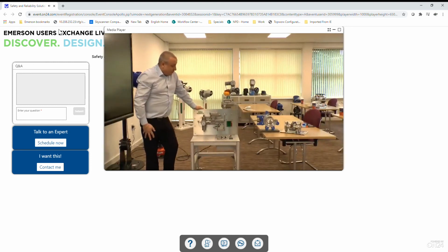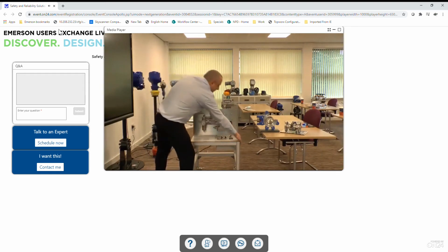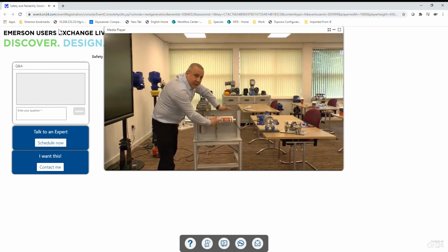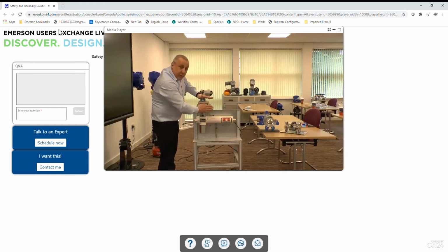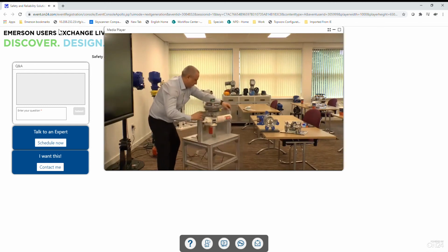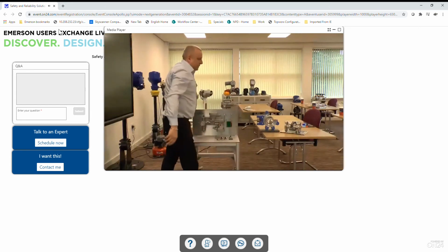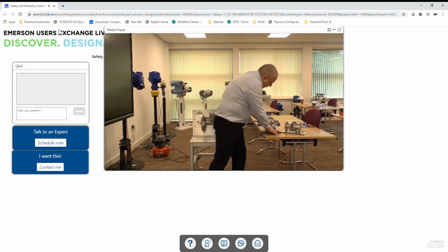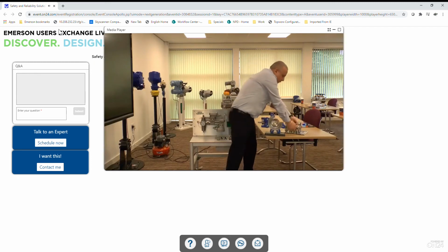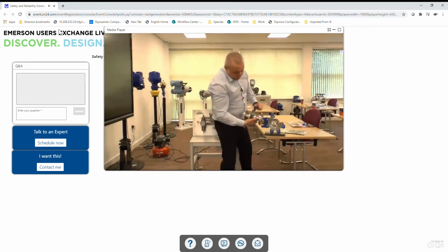So here we have an example of a typical valve actuated package. On the front is the controls. If I turn it around, you can see in this case a quarter turn actuator, and this particular model is a Scotch yoke type of actuator. We have a switch box to give us our electrical feedback, and this part represents the valve. Typical types of valve include a quarter turn, offset or triple offset valve, or a ball valve.